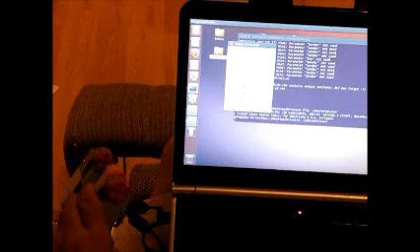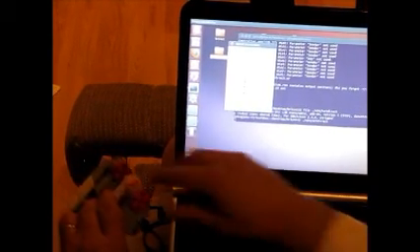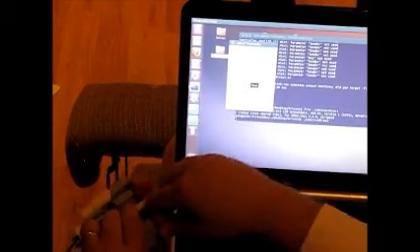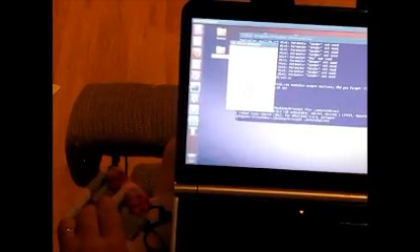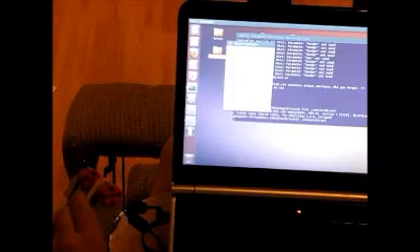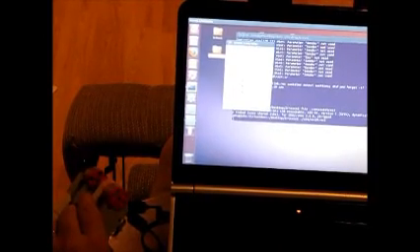That's using direct commands to talk to the NXT. We can hard brake it. It resists motion. You can still turn it, and then we can put it on float. It turns much more freely. If we hard brake it, it can be turning, but it's much harder. And then we'll go ahead and turn on B. Rotate it the opposite direction. Can you see that? Alrighty. And then we'll float both motors.